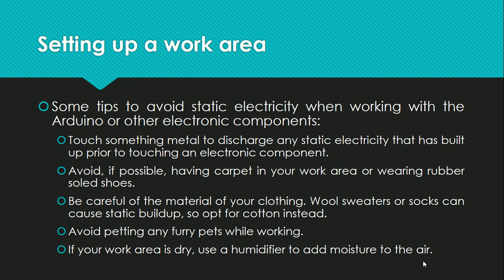And then avoid, if possible, having carpet in your work area or wearing rubber-soled shoes. Next, be careful of the material of your clothing. Wool sweaters or socks can cause static buildup, so opt for cotton instead, especially if you are in your working area. And avoid petting any furry pets while working, because friction can build static electricity. And if your work area is dry, use a humidifier to add moisture to the air.